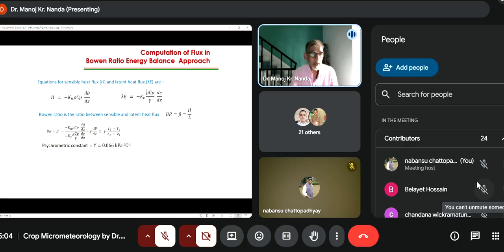So this defines the vapor capacity, or you can say the moisture capacity of the air pockets, when it is multiplied with E, or vapor concentration when it is multiplied with E. E means vapor pressure. Vapor pressure and vapor concentration relationship is defined by this formula.